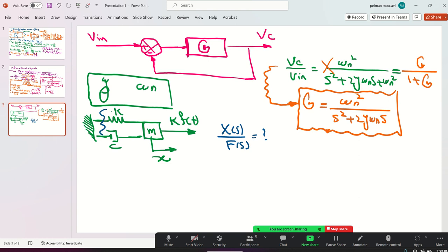You know, from vibration or dynamics, you have to cut the system from here. When you're pulling to the right, you have a reaction force from the spring and damper. Even if you're not a mechanical engineer, when you were a child and you were pulling a spring, it tried to pull back your hand. So that's a reaction force. This Kx, here X is 0, that's right. And C x dot. Now I'll take you to the ME 220 course that you passed here at San Diego State, and calling Mr. Newton, the sum of the forces in X direction is m x double dot. Now you have m, mass, despite the first system that wasn't spring and mass.